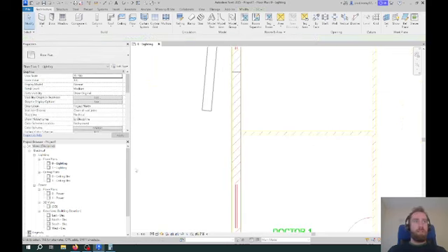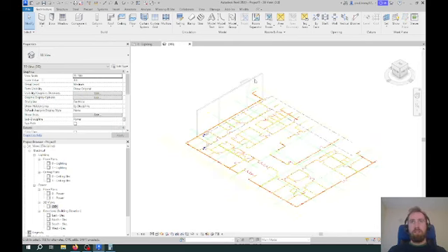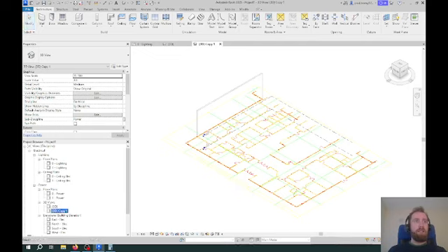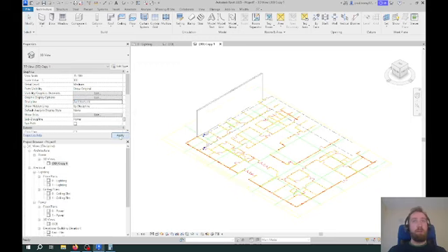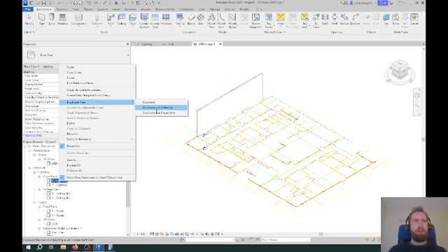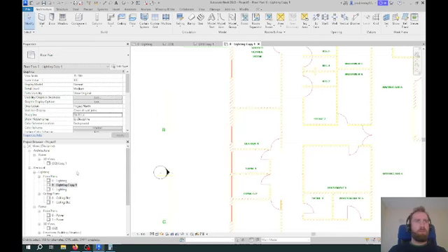Shown over it. So one way to check that is in our three-dimensional drawing. Yeah, we can see that the wall's been drawn over that. So I'm just going to undo those other two walls. Now we can't really view the wall in this drawing because this is an electrical drawing. So if we want, we can duplicate that view with detailing and change its discipline into something like architectural, which by default will allow us to edit and move the wall. So you can see there I can choose it in an architectural view. I'll also create a plan view in architectural for this, just to highlight what I mean even further.